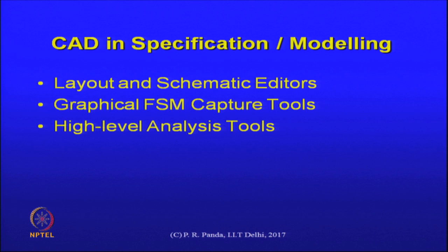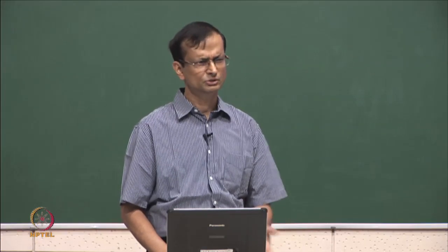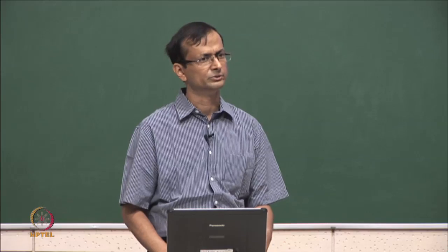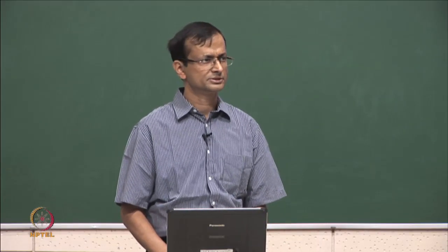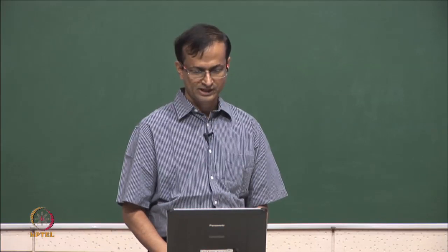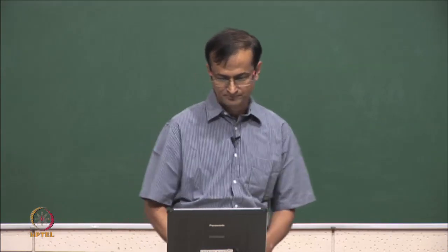It is possible that we make some mistakes in the specification of those conditions. That is also part of the specification. It could be that we have written that condition in a way that that condition is never true. You can write some expressions that never evaluate to true. So, some analysis one can certainly perform that just works off this specification that has been captured in the form of a finite state machine.